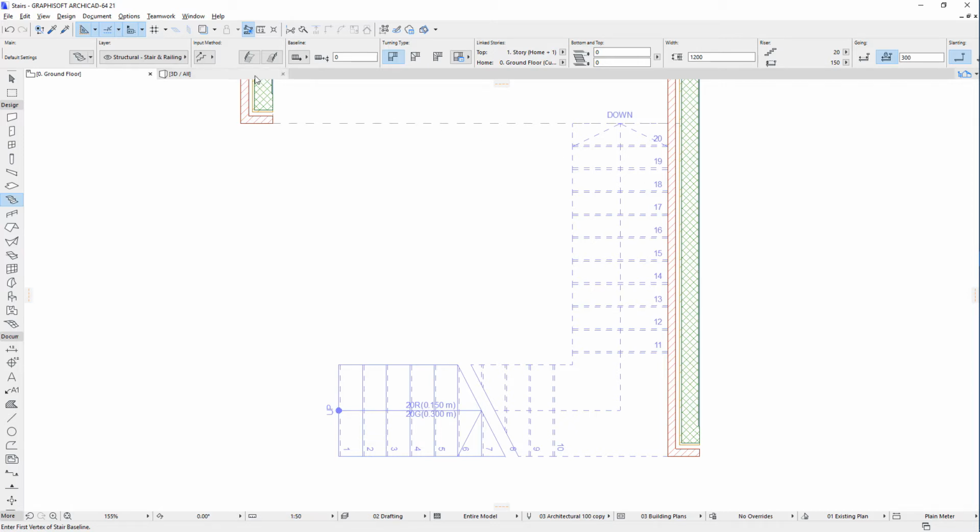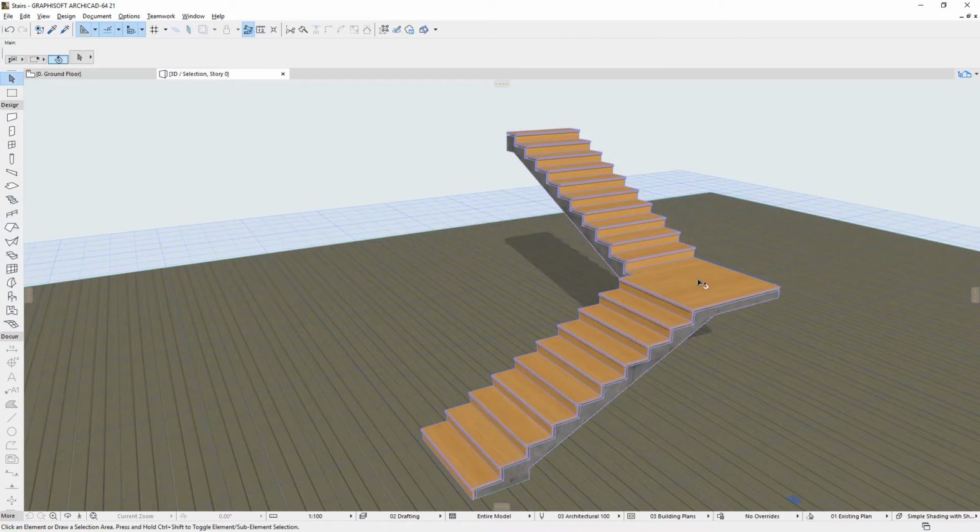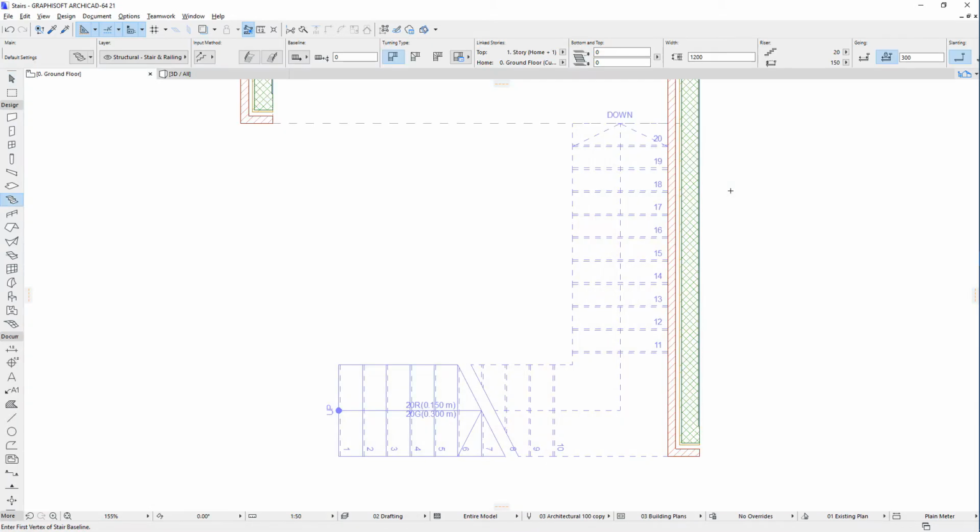Therefore, both 2D and 3D stair parts are based on and created from the same model database using the very same stair geometry parameters. Yet, the 2D stair symbol is not a direct vertical projection of the 3D stair model, but rather is generated independently. This ensures that ARCHICAD stairs comply with various customizable floor plan representation standards and rules.